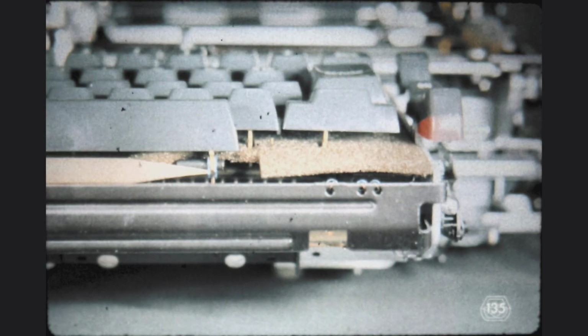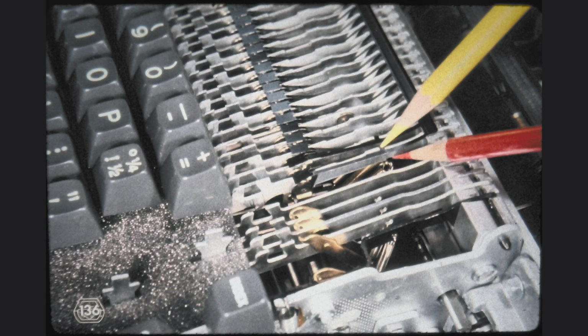With the pressure retainers on the indicated pivot point for the spacebar, it is possible to limit the sideways play of the spacebar. The final position of the spacebar must of course be checked with the central section of the machine case in position. Before you reinstall the case, be sure to check whether all the keylever pawl springs are properly installed and that all the pawls are correctly positioned.